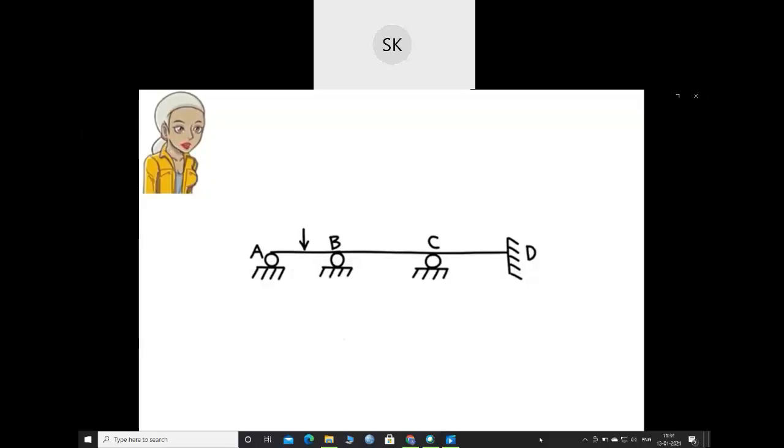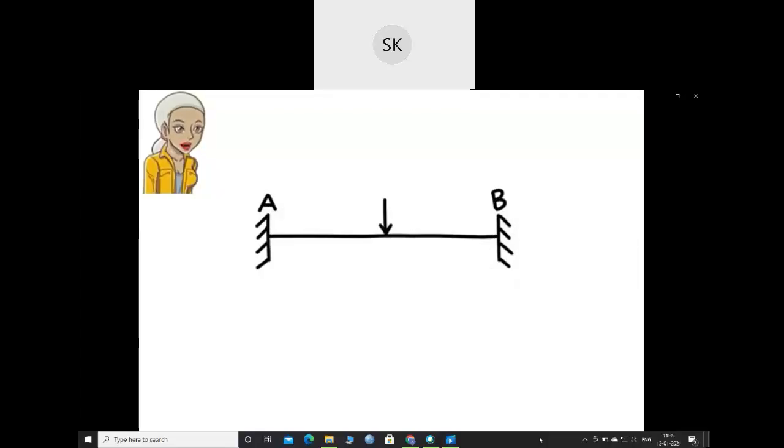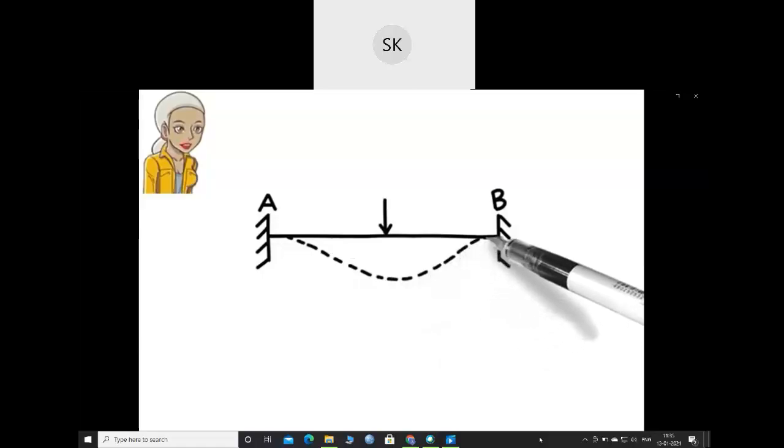This beam is similar to the beam in the previous example. Here, however, there is a fixed support at the right end of the beam. The beam deflects downward in segment AB with a clockwise rotation at A and a counterclockwise rotation at B. The rotation at B forces the beam to deflect upward in segment BC, which in turn causes the beam to rotate clockwise at C. Consequently, the beam deflects downward in segment CD with zero rotation at D. The location of the equivalent concentrated load is the geometric center of the area, which can be written as x equals L over 2 plus L over 6 times B minus A over B plus A. Since L is 12, A is 1, and B is 3, we get x equals 7.